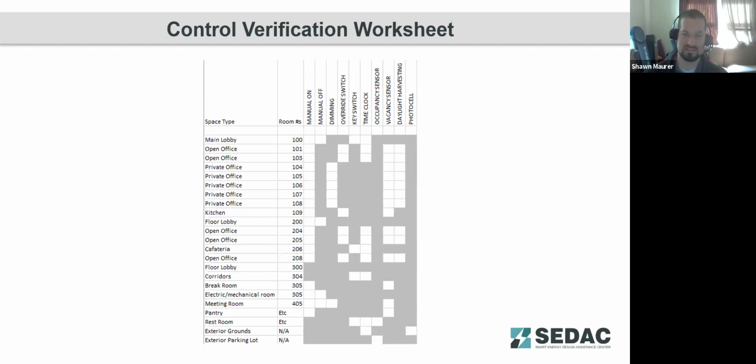If the classrooms have the same orientation and geometry, then you can do a sampling protocol and essentially just commission every few rooms that have the exact same geometric setup. And that includes orientation of the room, not just the shape of the room. And so that's why you can take that tabular format and expand it out to the different rooms with different geometry types and create a verification checklist. This kind of helps speed up the generation of the documentation you need for that commissioning process.